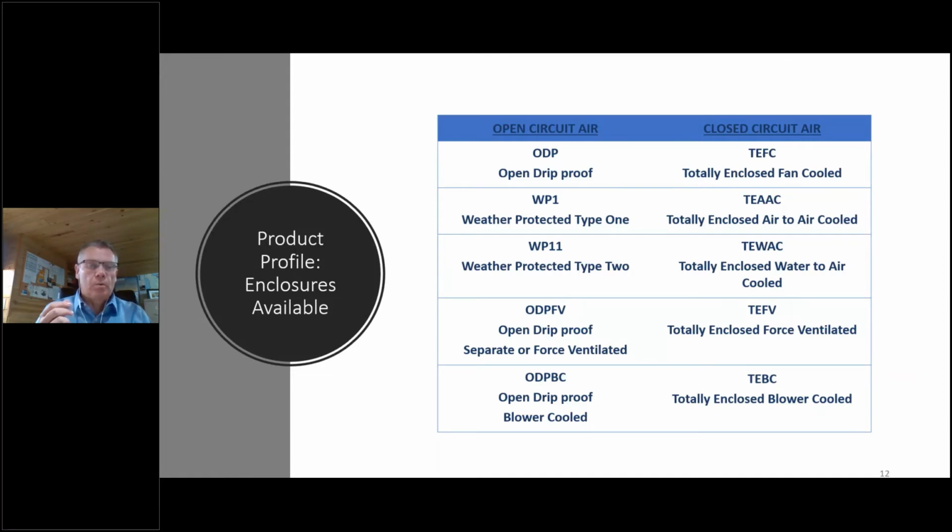As you move up into larger frames, you may start moving into totally enclosed air-to-air cooled or totally enclosed water-to-air cooled. And there are also abbreviations around force ventilated and assisted, separately ventilated, or blower cooled motors. I'll show you some examples.